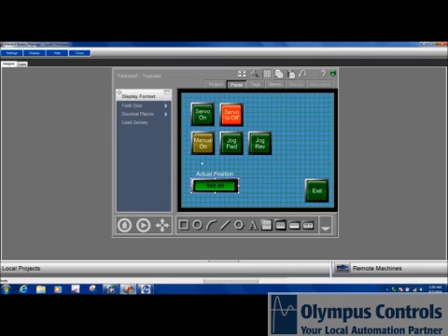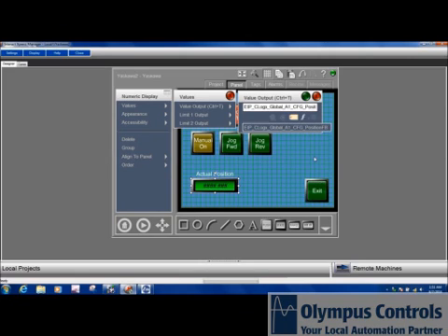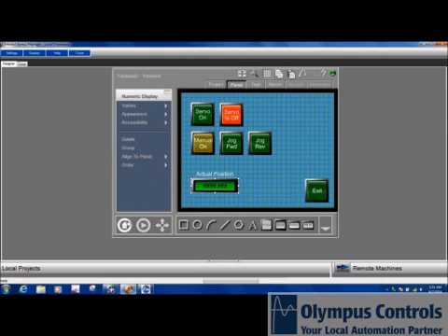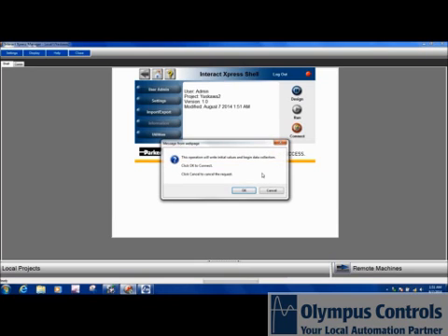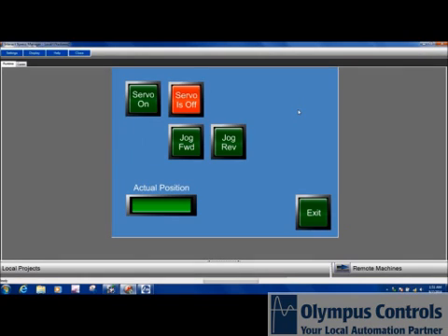I'm going to change the appearance of this, and let's give it a few more characters and another decimal place. And now let's connect it to our position feedback tag. It should be position feedback right there. Okay, now let's run this. And we're now getting actual position feedback. So our servo is still on. Let's turn on manual mode and let's jog it. And we can see that it is moving the motor, and I do see the shaft turning and the positions changing.